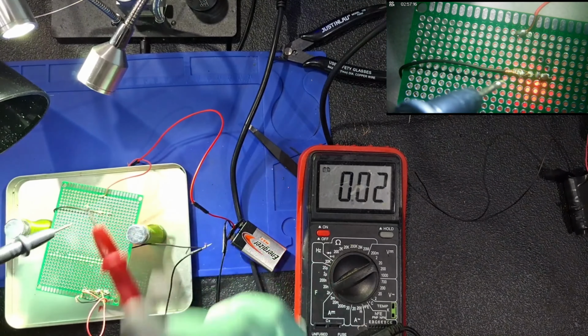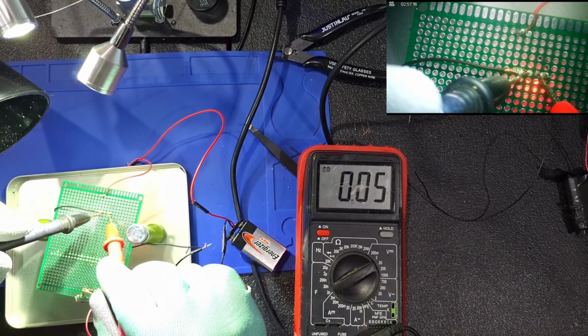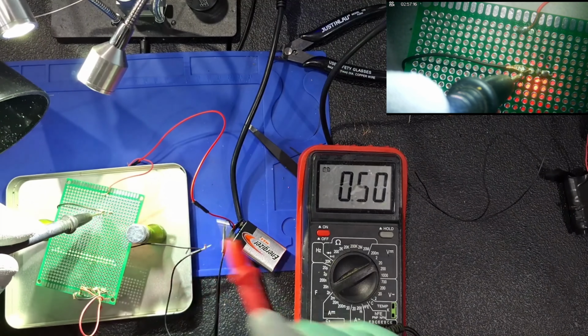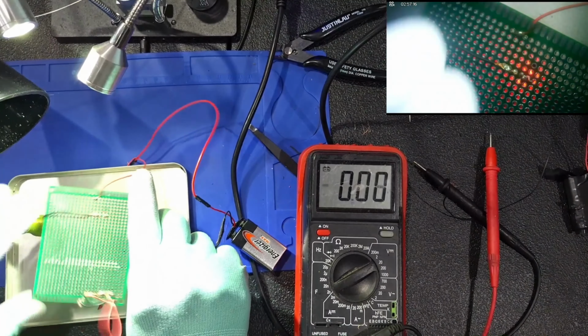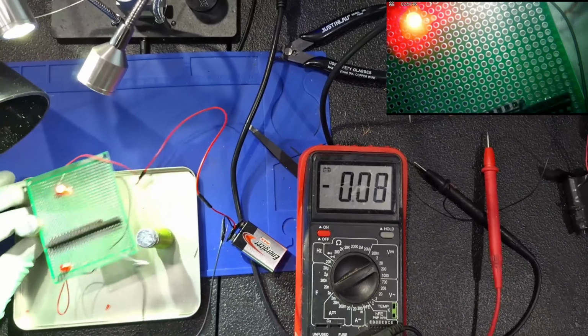So as you can see what I'm doing here with the multimeter, I have the dial turned to DC voltage and I'm just testing the amount of voltage that's going to the LED from the 9-volt battery. So like I said, simple: black probe to negative, red probe to positive. And if you have the black to the positive and the red to the negative, it doesn't matter, you just get a negative value on the multimeter, which is fine.